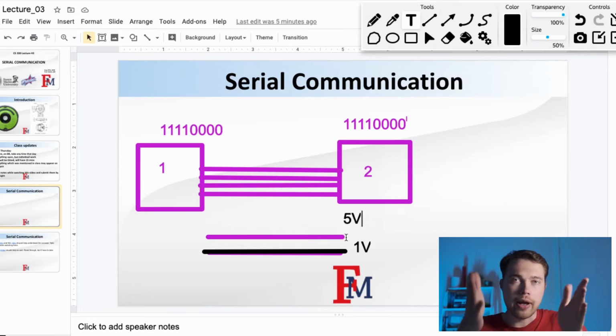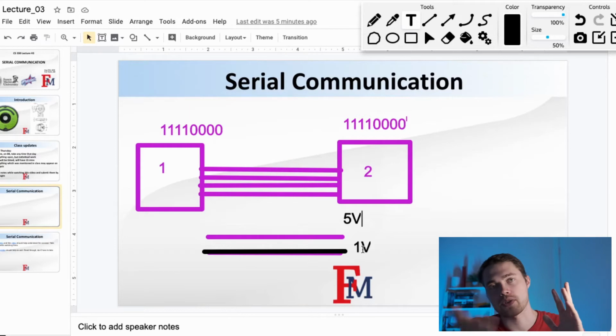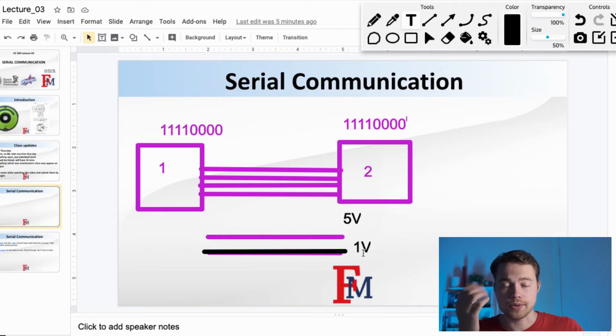So anyway, you have two wires, right? You measure voltage on both of them, and you find the difference. So you deduct the ground from whatever this is. Ideally it should be 0, so it should be 5 minus 0, but let's say something happened and the ground is not 0 volts anymore, it's 1 volt. In this case, you'll go 5 minus 1, so it's 4 volts.